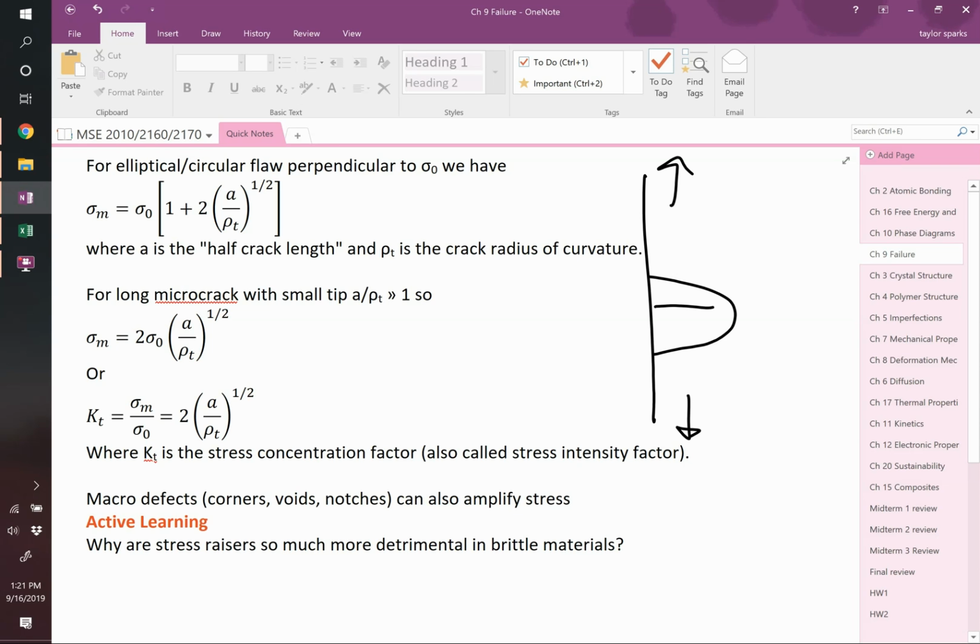Why on earth would it ever do that? It has to have a driving force, right? And in a ceramic, when you're stressing it, the stress that you apply to it is that driving force. Let's imagine I'm stretching all these students apart, I'm pulling them apart. They all would like to be some equilibrium bond distance. If I pull this whole thing apart, eventually they say, it's costing us so much energy to be stretched apart that we'd like to actually sever, create a bunch of dangling bonds, even though that costs energy, but then all these other atoms can go back to being some equilibrium distance apart. That make sense? So the surface energy is lower, basically. In a ductile material, it's going to have a higher surface energy penalty.